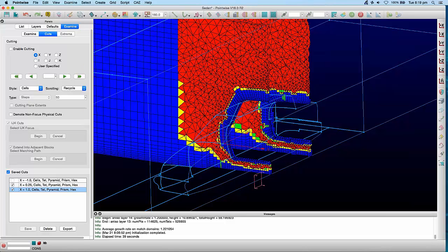One area where we have actually looked at it, and I guess that's where we looked with the adjoint solver originally, was the brake ducts, because the cooling to the brakes, that's all underneath, and that's actually not a controlled item. So GRM have the flexibility to design those brake ducts how they like, and they actually are bifurcating ducts. So they come in as one and then they split into about three. You've got it down to two now. And clearly you want uniform airflow through each of the ends of that.